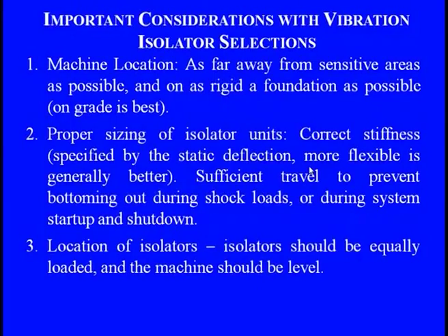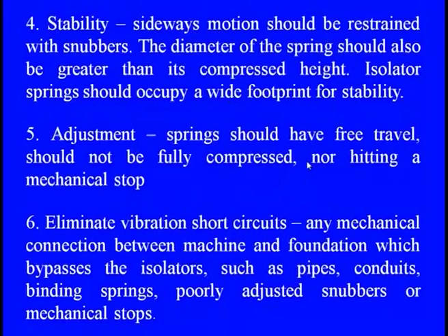The third important thing is the location of the isolator. The isolators should be equally loaded with the machine, and the levels should be absolutely the same for the isolator and the machine. The fourth is stability.